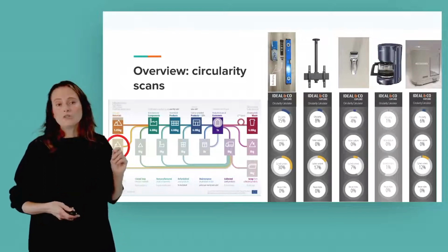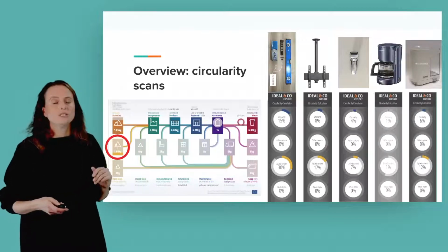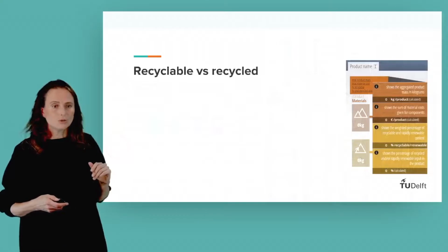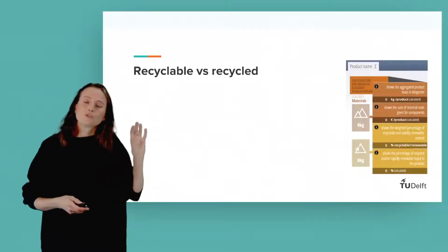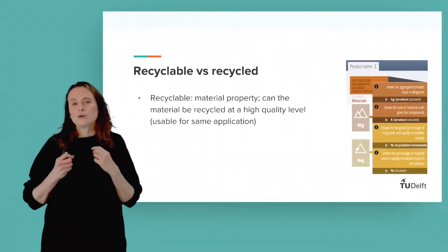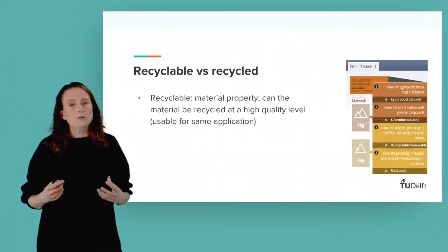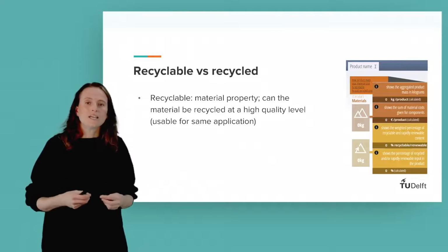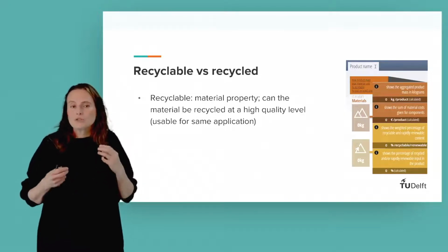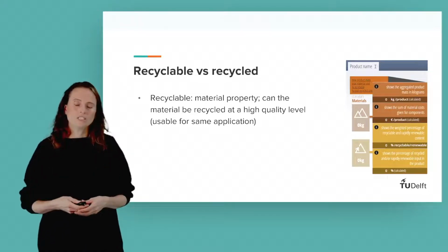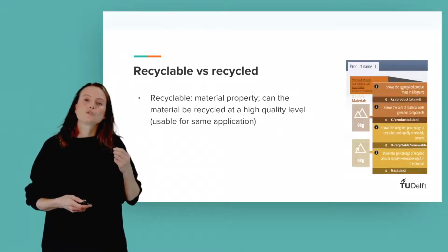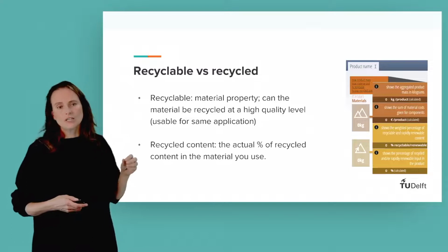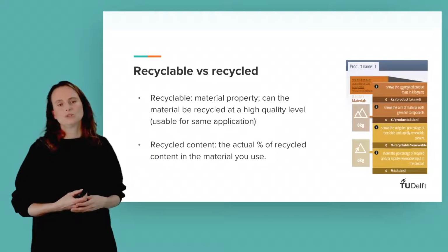A nice question of Ewald considered the difference between recyclable and using recycled content. Very good question. The first one refers to material property. So a material is considered recyclable if you could use it again at the same quality level, for a similar quality application. Whereas recycled content refers to the actual percentage of recycled material that is being used in that part or in that material.